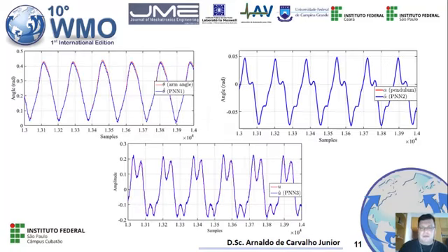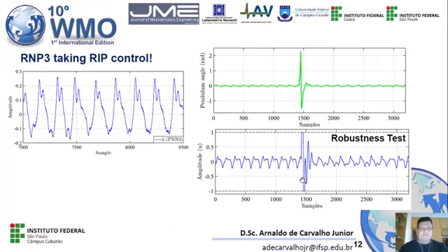Second, here we have the results of the learning. In the first figure, you can see the real arm angle signal of the pendulum in red, and in blue the PNN1 output, very close to the result. The second, from the pendulum angle output and the PNN2, you cannot see any difference, and the control signal U and the PNN3, also very difficult to see any difference between them.